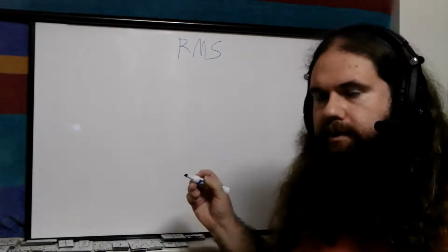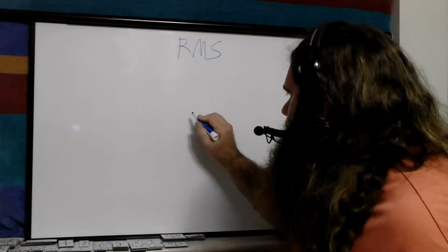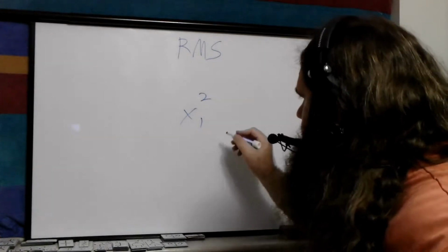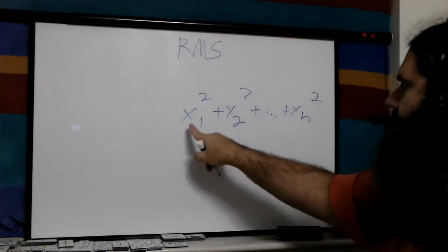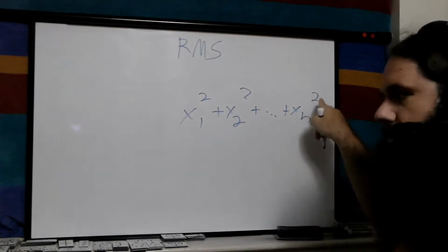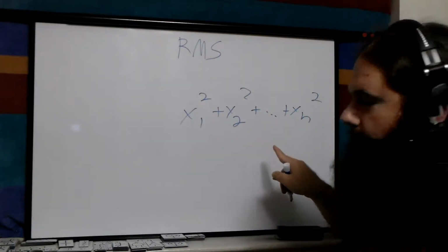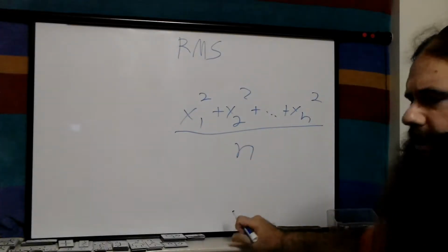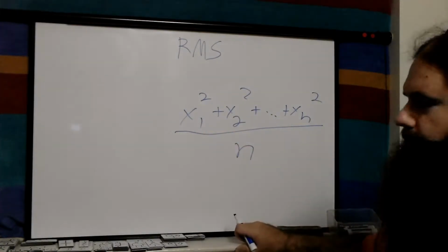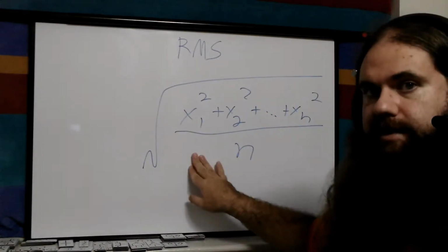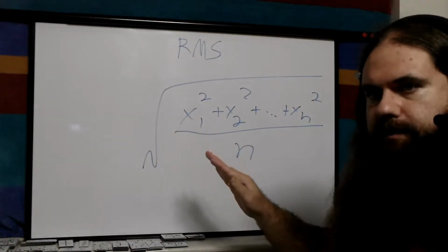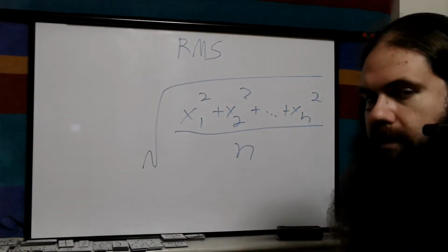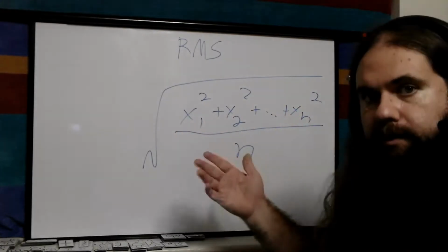What is root mean square? So let's say you just sample the voltage and you say, okay, right now it's that, square it. So that gets rid of the negative sign. So you just take a sample and square it, a sample, square it, all the way up to n, which is however many, and then add them together. Divide all that by n. That's a mean, except it's a mean of squares. And then square root. And for reasons, the squaring actually makes this much more useful. So if you took all those samples of AC that were over 120, under negative 120, and so forth, and did this, you'll get roughly 120.